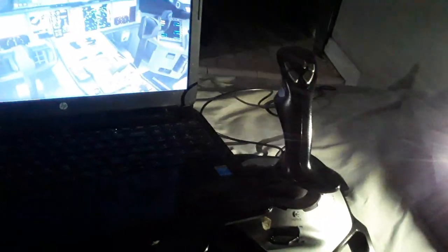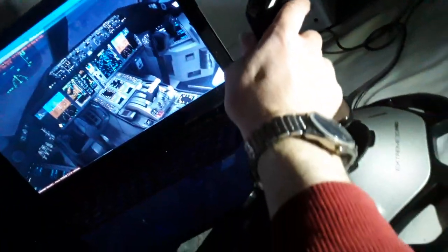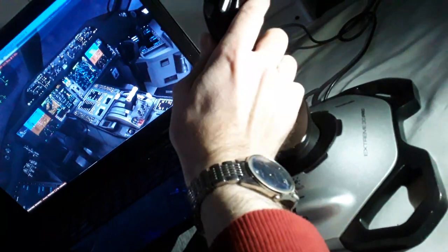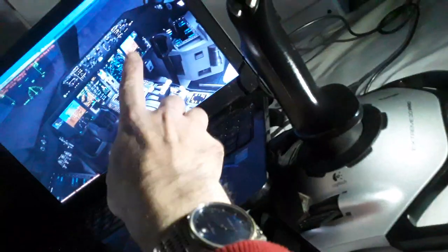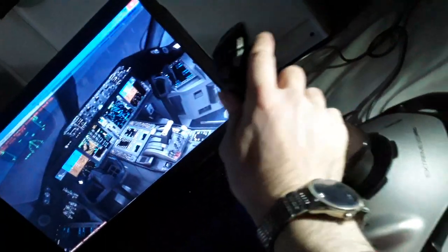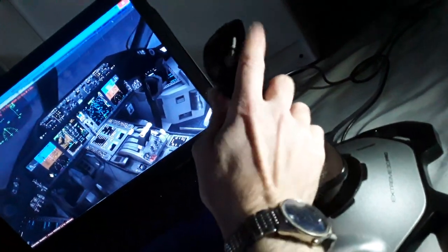Same as in the Airbus, you use it for the Boeing aircraft also to control the yoke of the Boeing 787. You can see the side stick deflection is proportional to the yoke deflection. All the flight controls are interconnected. The captain and the first officer move together in flight unless they have a failure. They're not like in the Airbus, where you have the side stick priority for either left or right side.